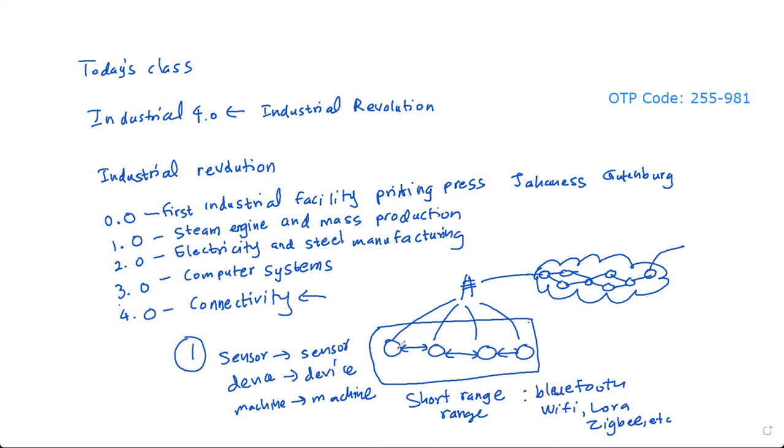So we can install these modules, Bluetooth, Wi-Fi, or whatever communication module is required, in these sensor nodes, and then by installing the same module in the other sensors also, we can establish the communication between those modules, right? If you want to communicate using LoRa, then we need to have LoRa modules installed in both devices. The transmitting device and the receiving device must have the LoRa module, so that the receiving end can decode the data that has been transmitted by LoRa. Therefore we can install the necessary modules in these sensors, and using that we can establish communication between devices.